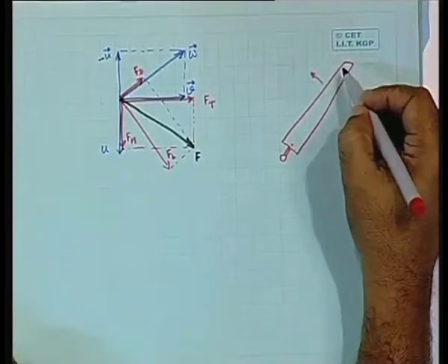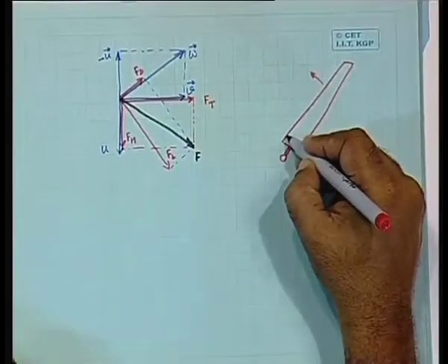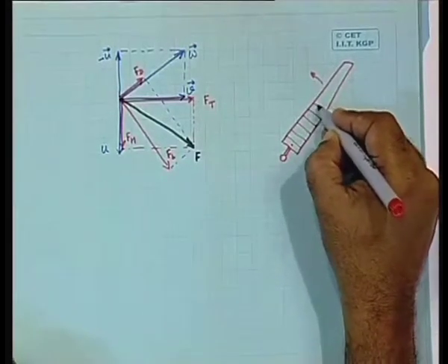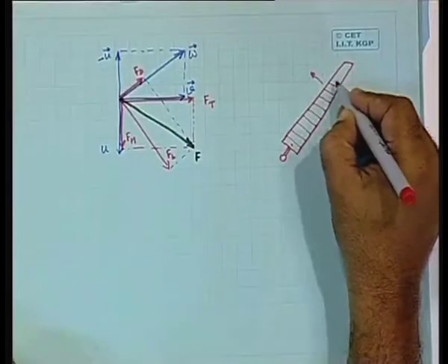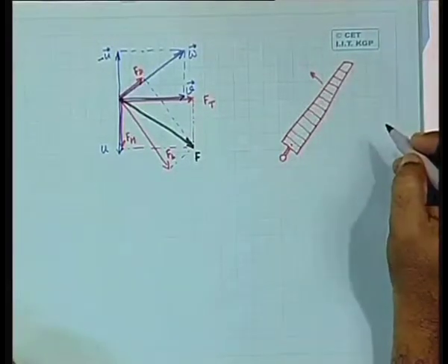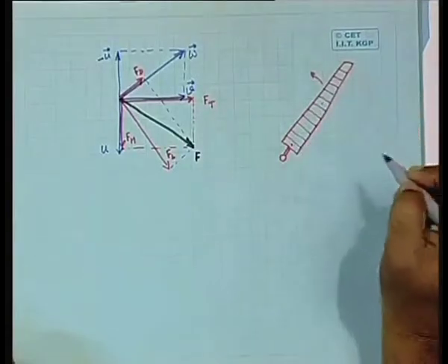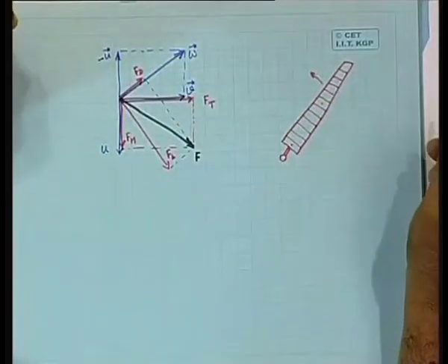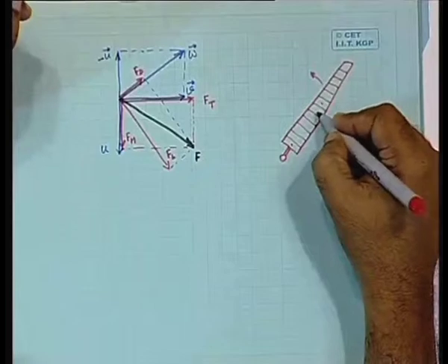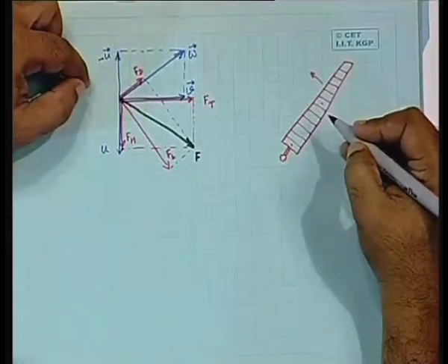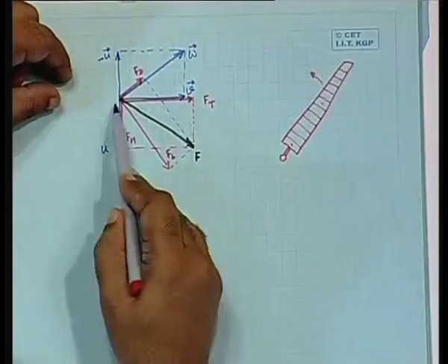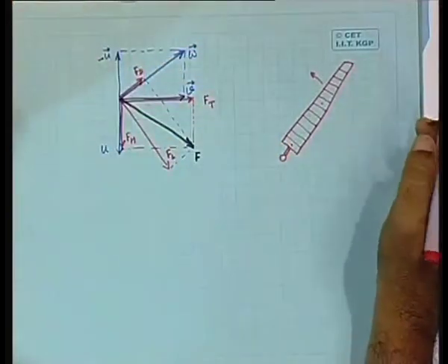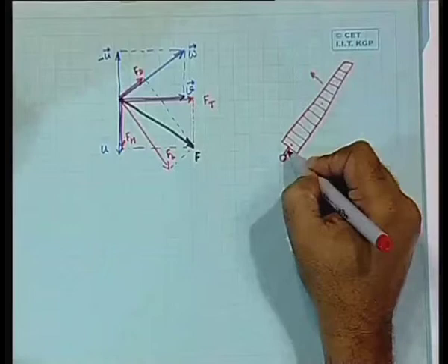So in order to do this calculation, what we do is we divide the blade into small sections. Okay. Then take one of them, and for that you can draw this kind of a force diagram. As you go to another, the magnitudes will change. The V magnitude will remain the same, but the U magnitude will change. Naturally, the direction of the W will change. Direction of all these forces will change. So we need to do this calculation for each section.